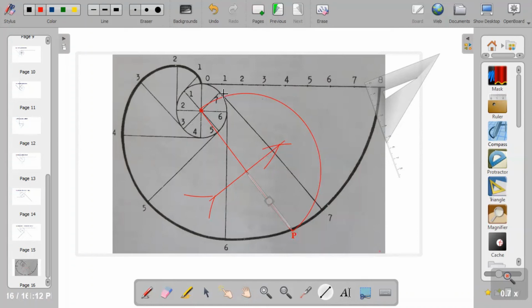I want to use another color. So I want to draw a line from the point of intersection of the semicircle and the base circle. So the line drawn from that point to point P is called the normal.